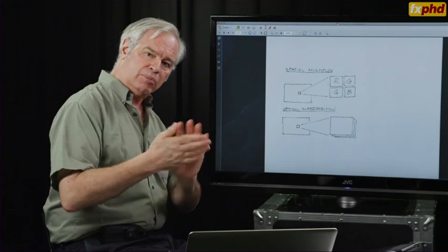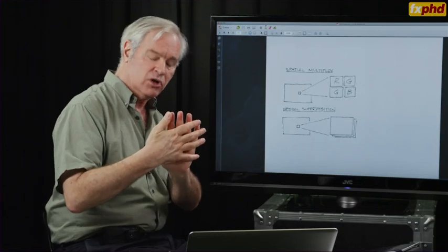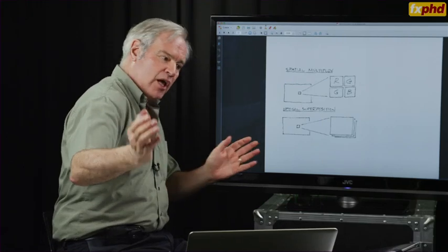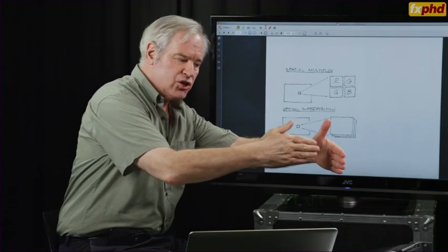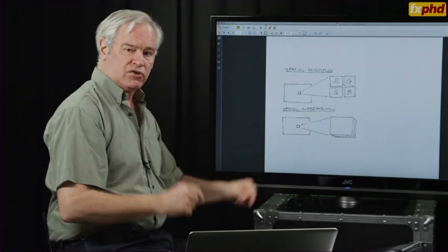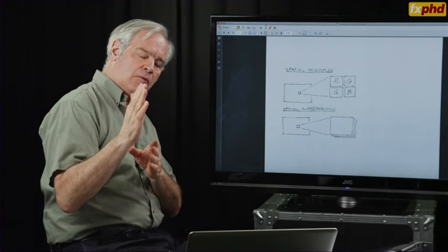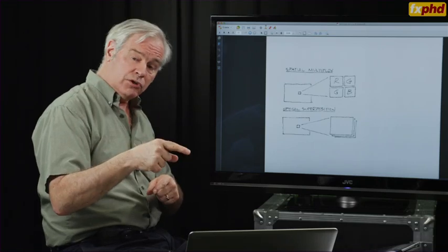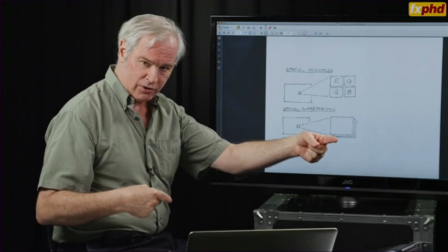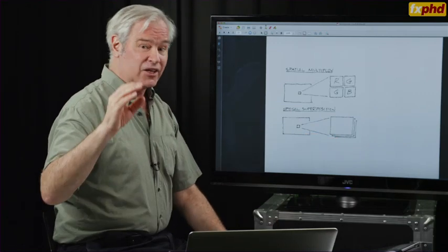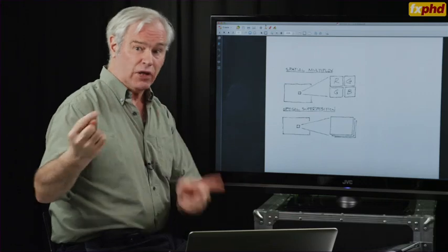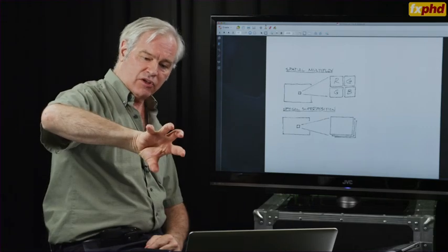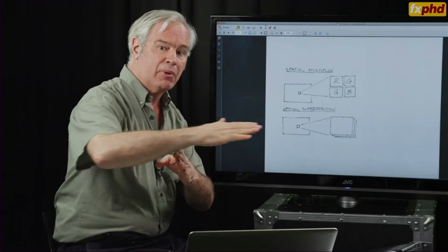So the red, the green, and the blue are laid right on top of each other. So there's some sort of optical separation at the camera and some sort of optical recombination at the display. Now, I've explained that you could use a beam splitter to separate those components at the camera. You can also use a beam combiner, which is basically exactly a beam splitter, just the light going the opposite direction. So red, green, and blue goes into this prism assembly, and the combined beam comes out.